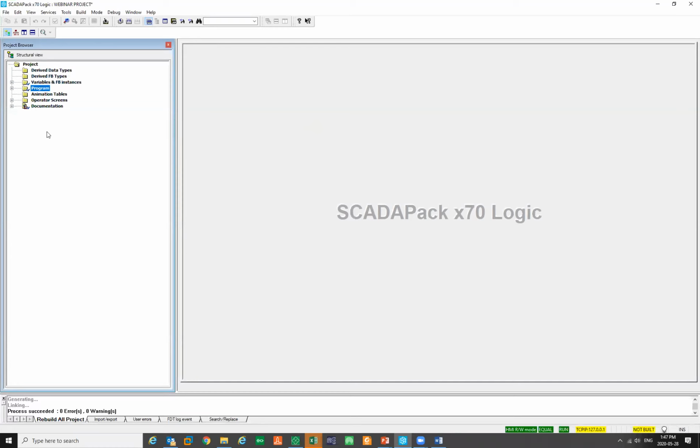This is, as I say, the Unity software that we've repackaged to work with the SCADAPack itself. These two folders here are where you would create and add in any custom function block types that you may have created. Any libraries that you want to bring in would populate any custom user-defined data types and user-defined function blocks in this area. Let's have a look down here.